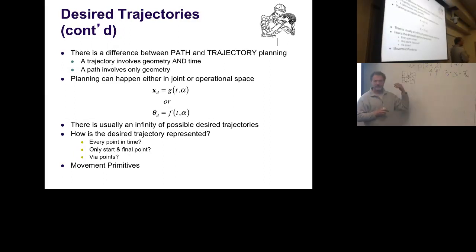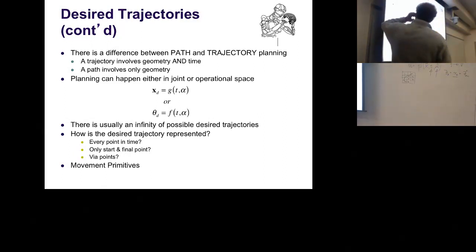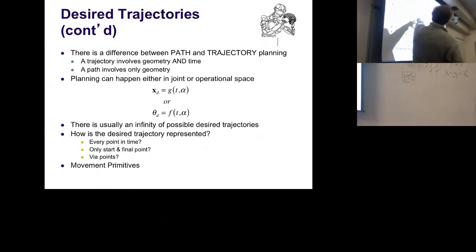Now, in a grid world, this is great, or if you play chess, since there is essentially no real dynamics in there. In a practical robot, you want to make smooth and nice movement. If you do jagged movement, it's really stupid. So trajectories are more important than control. We can plan now either in external space or in joint space.